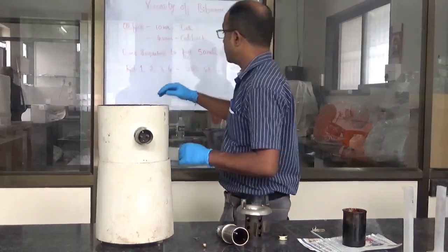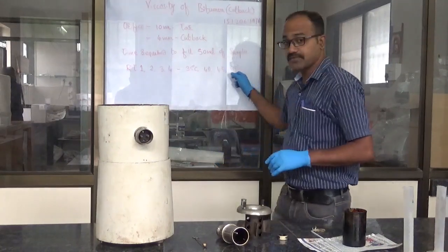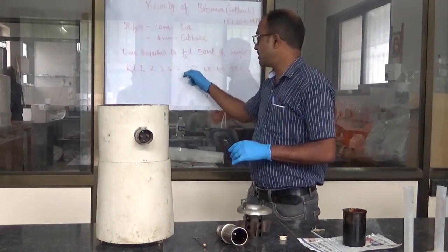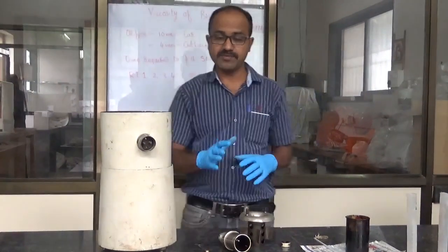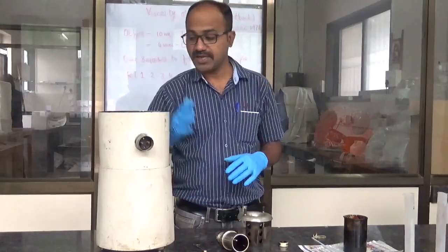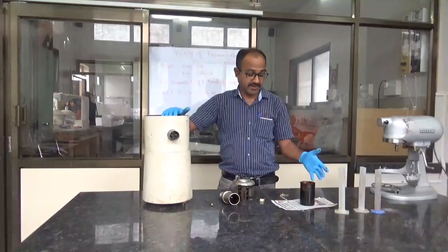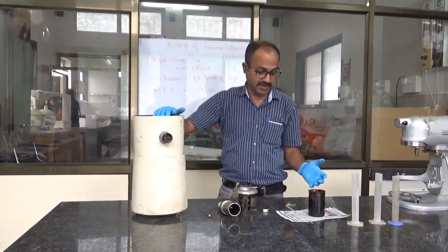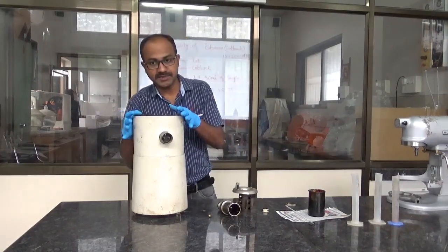Depending upon RT1, 2, 3, 4, you need to maintain various temperatures, 35 degrees, 40, 45, 55 degrees, whatever it may be, according to the sample. But when I am measuring the viscosity of a cutback, I don't need to maintain the temperature.